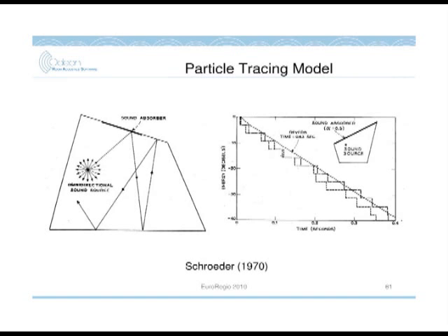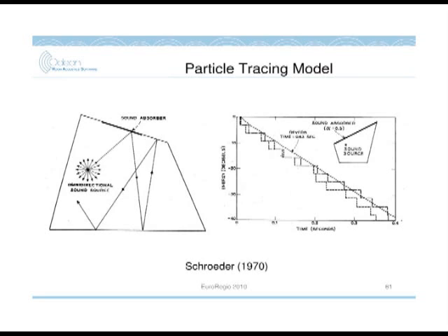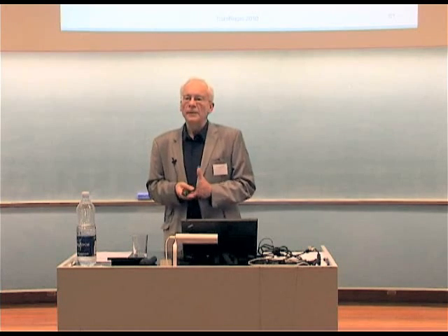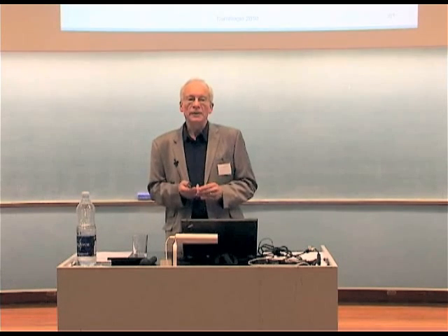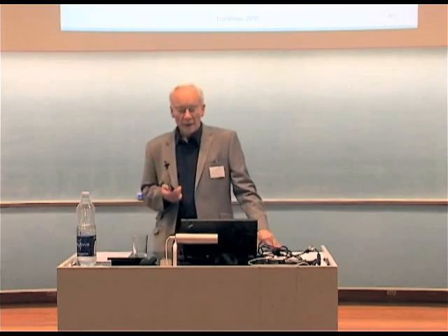Each particle is assumed to carry a certain acoustic energy, and then the energy is reduced according to the absorption of the surface. That means, if you look at the right-hand figure, you can create a decay curve where, for every time step, you add up all the remaining energy in the particles at that particular time delay from when they were emitted. And that works quite fine in any geometry and also with very different absorption coefficients in the room.